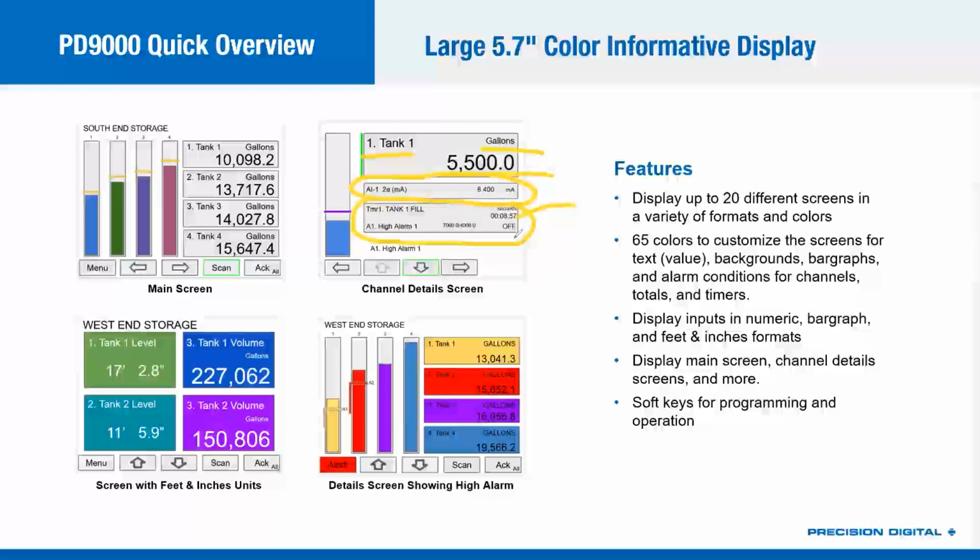It's showing me how long this alarm has been on for, what its current state is, what the set and reset points are, as well as the bar graph for display, just so again, I have a sense of what I'm looking at. And finally, in the lower right, what I'd like to point out is that you can have those colors change in alarm states. So you'll see here that I have an alarm state active. And so I have my alarm state line, which tells me where it goes in the alarm.